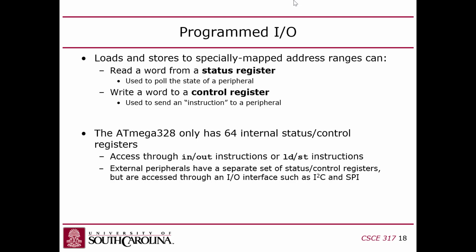So the two ways that you interact with hardware are programmed I/O, meaning that you read and write to special memory addresses, and interrupts, which allow you to write code that is executed whenever a certain event happens related to an I/O device, right? And so pretty much that's going to be the whole semester, is doing programmed I/O and writing interrupt handlers mostly. We'll also be debugging those things using a logic analyzer and lab equipment and a debugger. But generally speaking, talking to hardware and doing hardware-software interfacing is all about just this programmed I/O and interrupts.